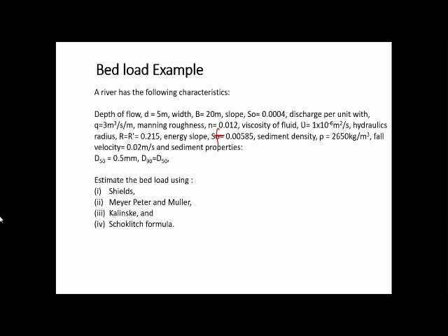And the sediment properties are also given, 0.5 millimeter for the D50. So just plug all these values into those equations, and then you will get the bed load transport rate. Maybe we can do one of them first, and then the rest you can continue at home.